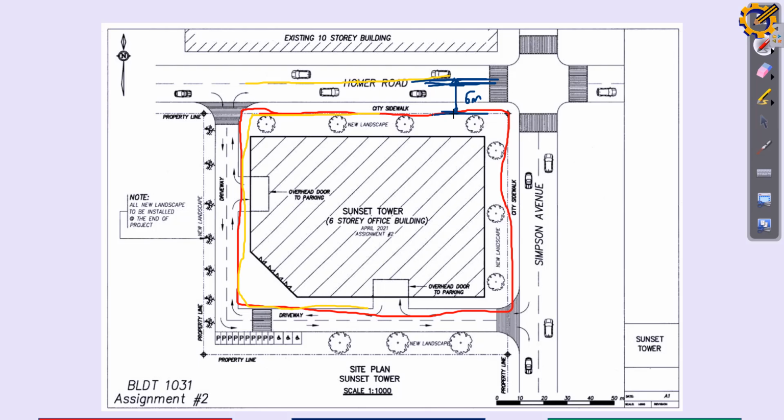And also from the boundary of your land to the wall of your building, it must be 6 meters. Another 6 meters, that's another 20 feet. So roughly from the center of the road to the first wall of your building itself is around 40 feet.